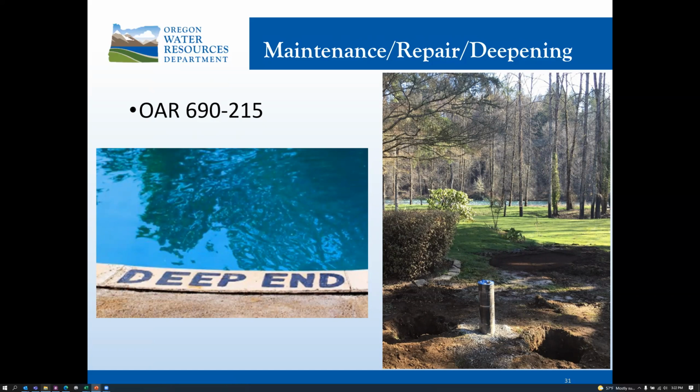So then we talk about deepening of a well. Only certain wells can be deepened, and the requirements of that play out in that only the following wells may be deepened without approved special standards: wells with an original well report that describes the construction, and that construction must meet minimum standards. And if that is the case, then that well report has to be referenced on the deepening well report.